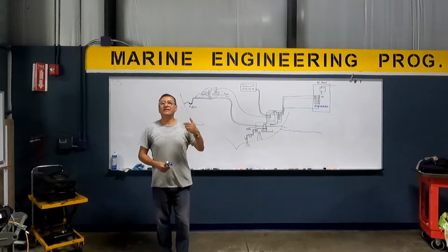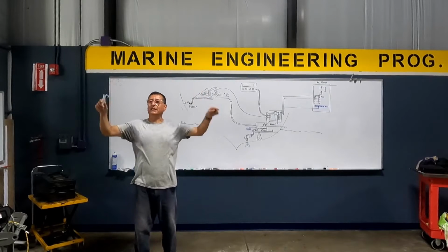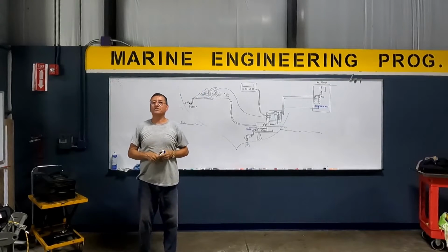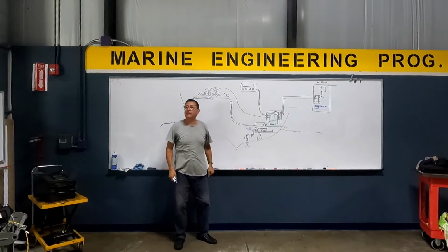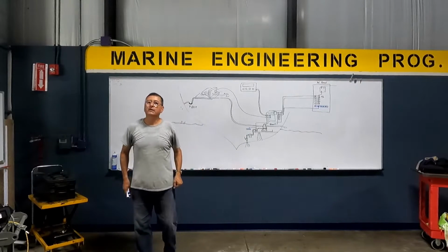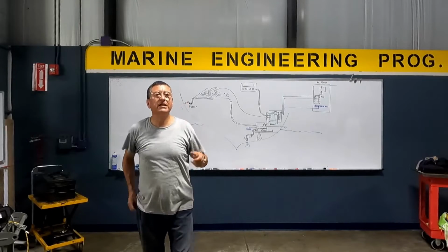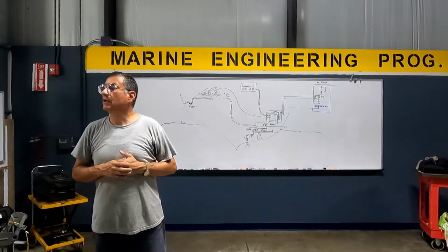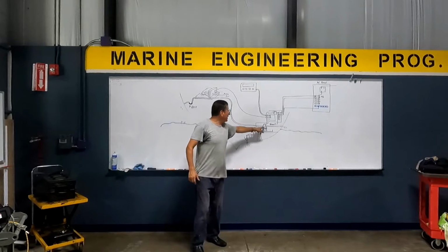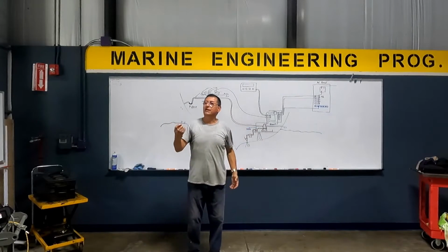Okay? You remember yesterday in the diagram of the refrigeration cycle, what happens if this raw water pump is broken? Yeah, overheats. Can you explain to me? Yesterday I explained in the refrigeration cycle what happens if that pump is broken. The high pressure switch activates. Okay, the temperature in the coil of the condenser increases.